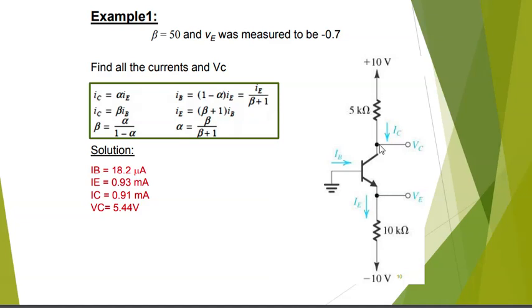But with the example that I told you, imagine this resistor was smaller and the current here was high, so the circuit was getting over current, then it would go to the saturation mode. This VCE will be negative, which is impossible. VCE is never negative. The moment that this VCE goes below 0.2, we say it went to the saturation. So when it goes to the saturation, we just assume VCE to be 0.2, and then we will analyze the circuit again from scratch.